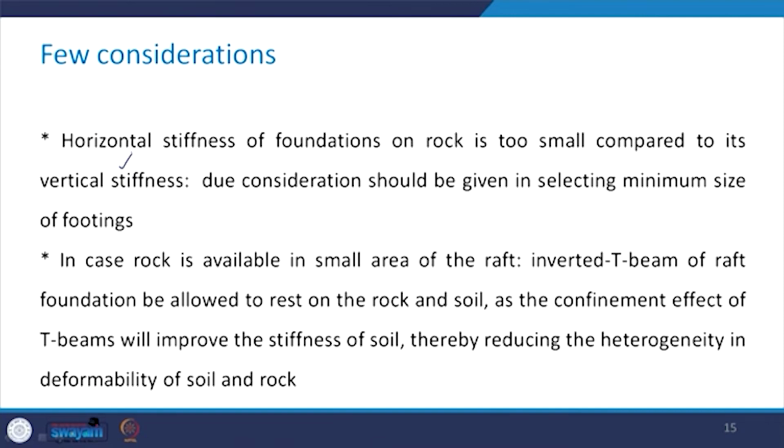We need to keep this in mind that the horizontal stiffness of foundations on rock is quite small as compared to its vertical stiffness, and hence due consideration should be given in selecting the minimum size of the footings. So, when you select the size of the footing, you should keep in mind this fact that the horizontal stiffness of the foundations on rocks is quite small as compared to that of its vertical stiffness.